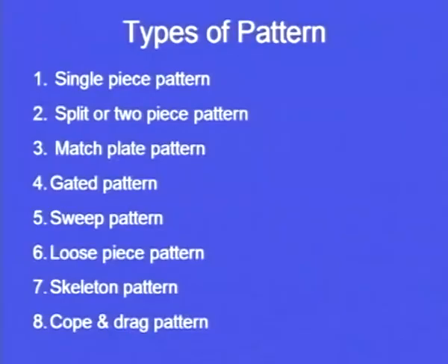And now let us see the types of patterns. There are several types of patterns, and we will see some important types of patterns. One is single piece pattern, another one is split or two piece pattern, third one match plate pattern, fourth one gated pattern, fifth one sweep pattern, sixth one loose piece pattern, seventh one skeleton pattern, eighth one cope and drag pattern. Let us study these in detail.